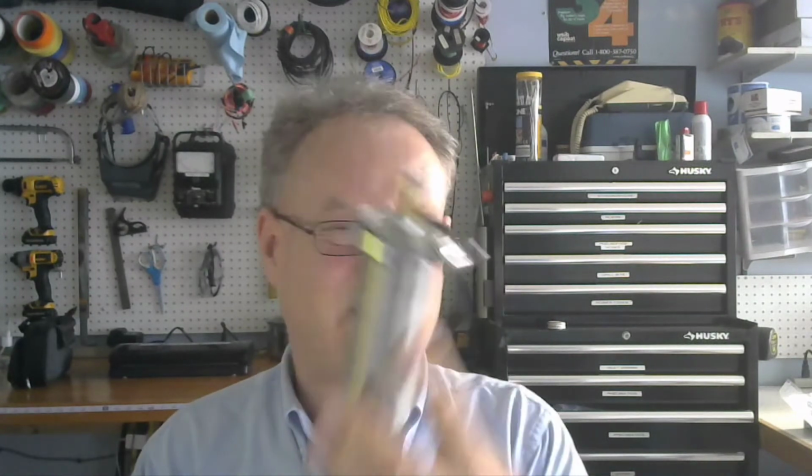Now, because it's small and there's no compressor filling it anymore because the power went out or the compressor died for some reason, I may only be able to run my actuator once or twice, but at least I can open that heavy hatch. At least I can lock that door. At least I can close that security gate or open up a gate or some kind of operating mechanism that's for safety, or some fire mechanism, or whatever it is.